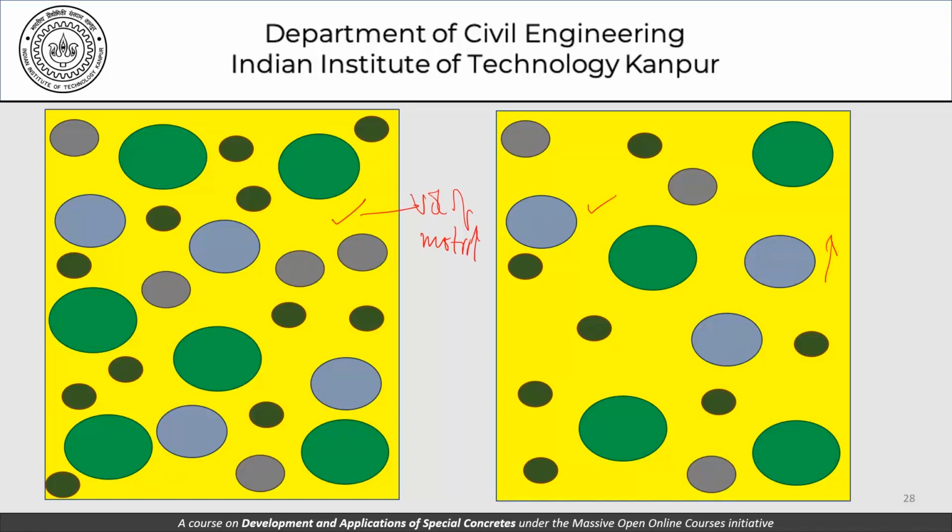What it means is that as far as the concrete is concerned, for example, in this case, this mortar should have the capability of carrying with it all these aggregates which are shown here. This mortar should have the properties or ability to carry these many aggregates together with it as it moves through pipes and is trying to be placed as a concrete.